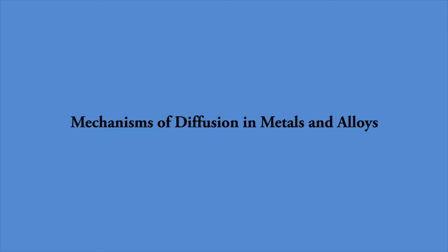Welcome to the 30th lecture of this open course on diffusion in multi-component solids. In this lecture, I will explain some of the important mechanisms of diffusion in metallic alloys. These include interstitial diffusion and vacancy diffusion mechanisms. I will also briefly describe direct exchange and ring mechanisms.